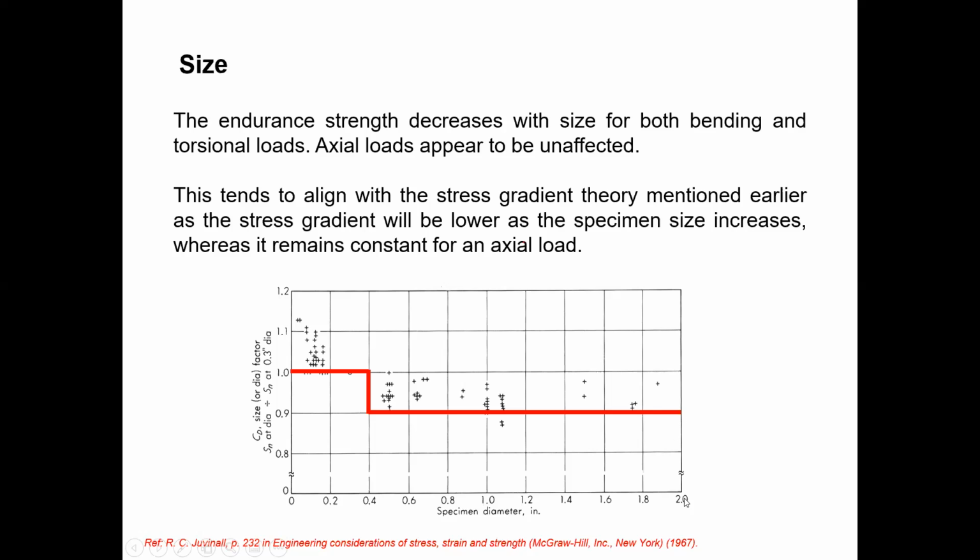We are not dealing with cases above 2 inch diameter. Here we are dealing with questions lower than 2 inch. In the question they will not provide a value more than 2 inch. So that is the size factor effect. It also does not affect the 10 to the power 6 cycle.